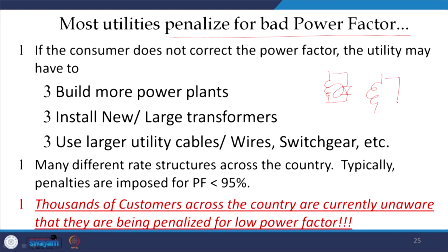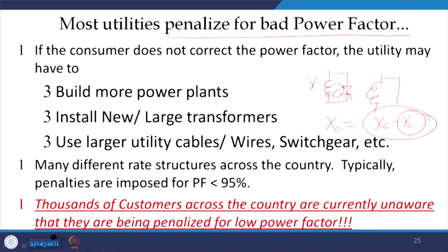Thereafter, you can have a capacitor, and thus a value of the inductor, you can control the triggering of these thyristors, and the value of the reactance you get is essentially Xc minus XL, where XL will be a function of this triggering angle, and thus you can change the effective value of the capacitive reactance so that it does not tune to the particular harmonic.